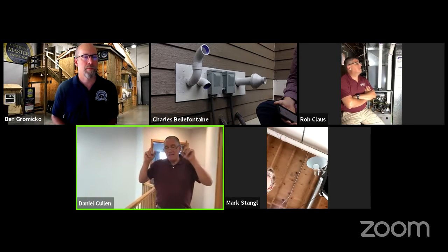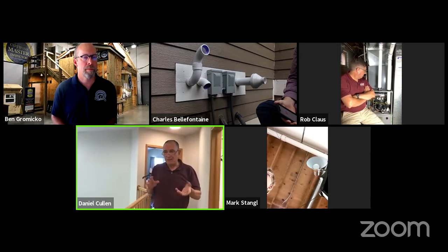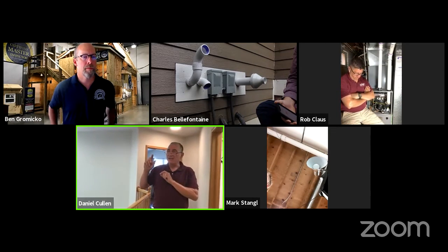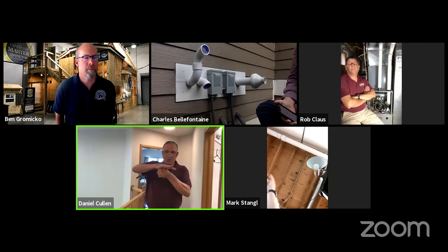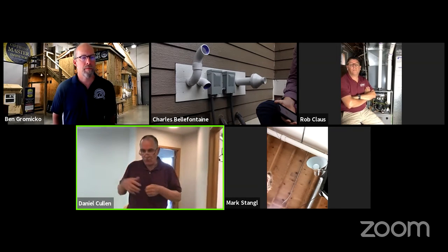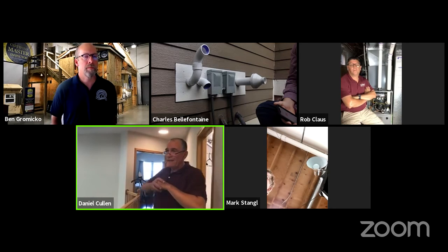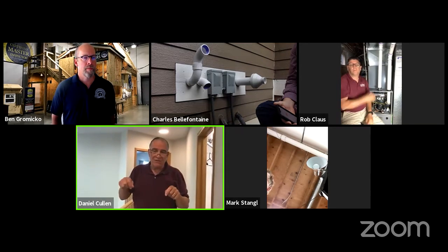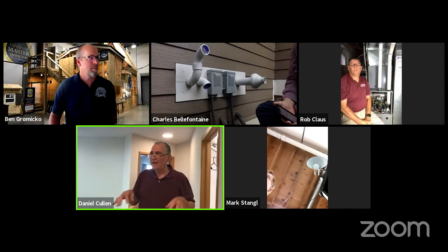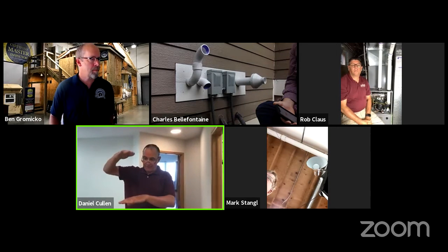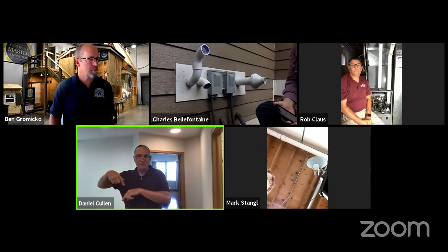If we allow that up into the attic, we not only lose that money that we spent heating and cooling it, but we also create that risk for condensation in the attic. The way to avoid that is to put our thumb on the straw. I had a local weatherization company come in. They put insulated covers on every single can light. They sealed all the gaps in the partition walls at the wall plates, every single penetration, plumbing, vent piping, conduit, everything, sealed it perfectly, installed baffles all the way around, and gave me about 12 inches of cellulose on top of the existing fiberglass batts. And it's made an incredible difference here.